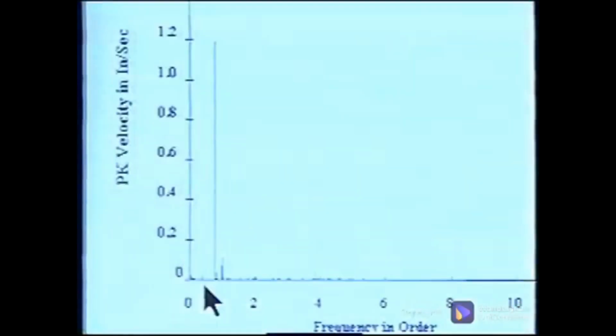Let's take a look at a case history of a belt-driven pump to see just how much energy can be added to this system from the belt drive and how a few corrections can drastically reduce the vibration from the belt drive. This high-resolution spectrum is from the sheave end of the motor in the horizontal direction. There are only 3 peaks, with the smallest one being the speed of the pump. The next one is motor turning speed, but the largest peak is belt-related.